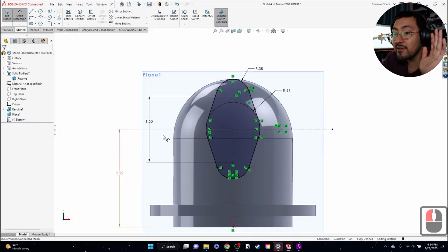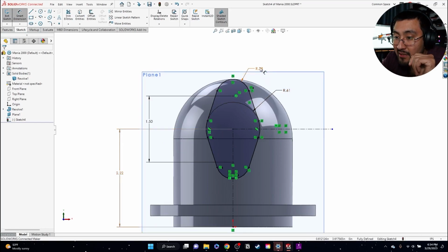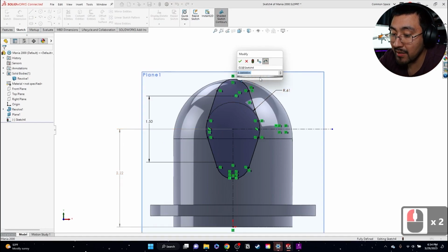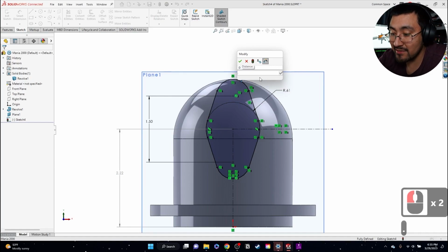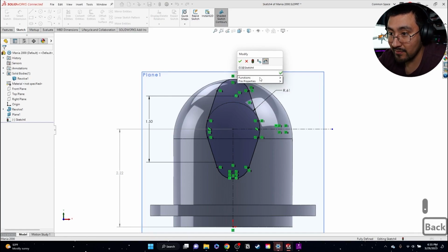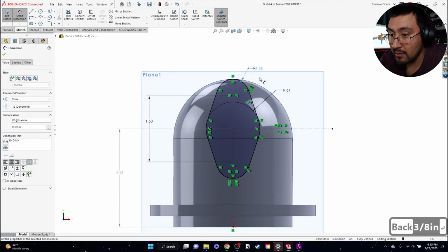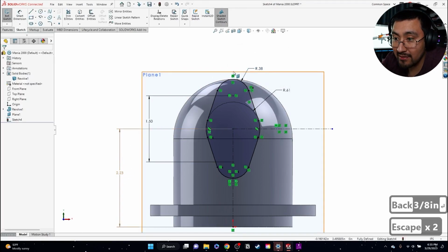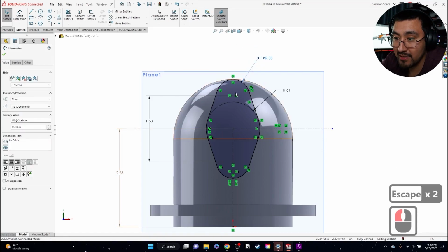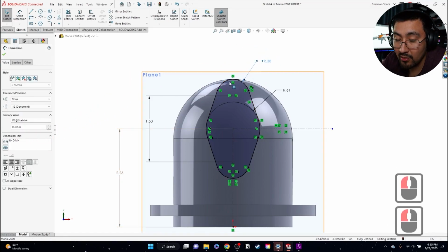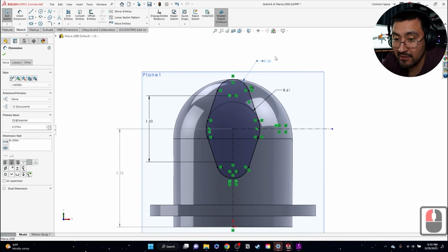Now typically you wouldn't see this in many other drawings. I think it's just an error on their part. But it's still just an assumption. So for me, I know it's at 3/8. And then you see that right there? It says 3/8, but because of the number of significant figures, we actually get 0.38 here, but the actual measurement is 0.375.